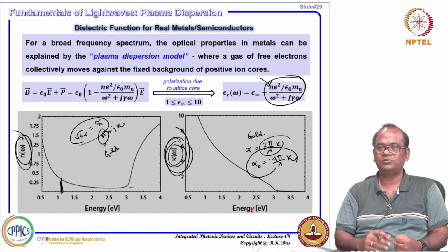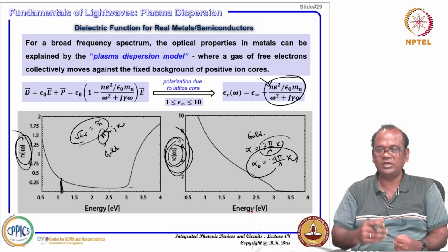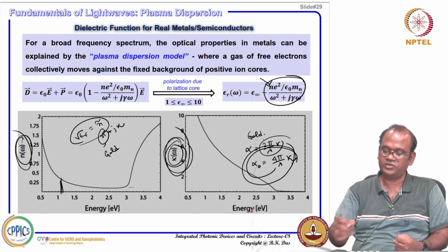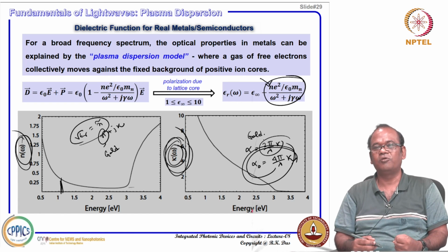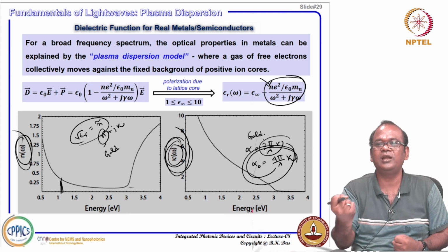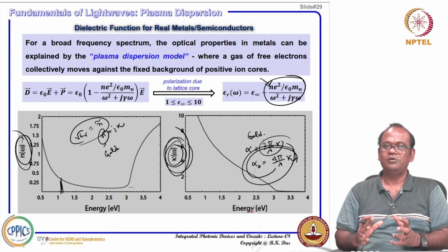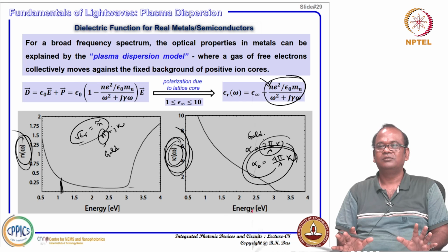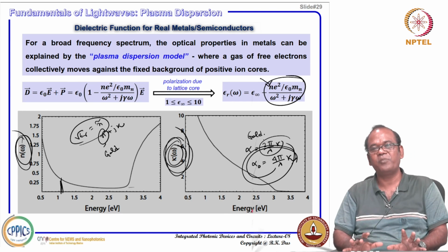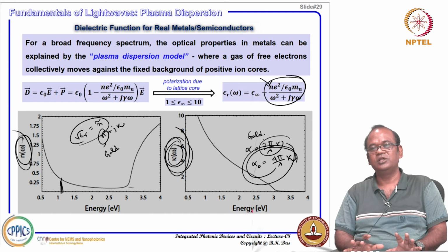Phase control can give you phase modulation, and the so-called extinction coefficient control can give you attenuation. You can have a variable optical attenuator. This is the basic thing exploited for photonic integrated circuits using the CMOS compatible silicon photonics platform.